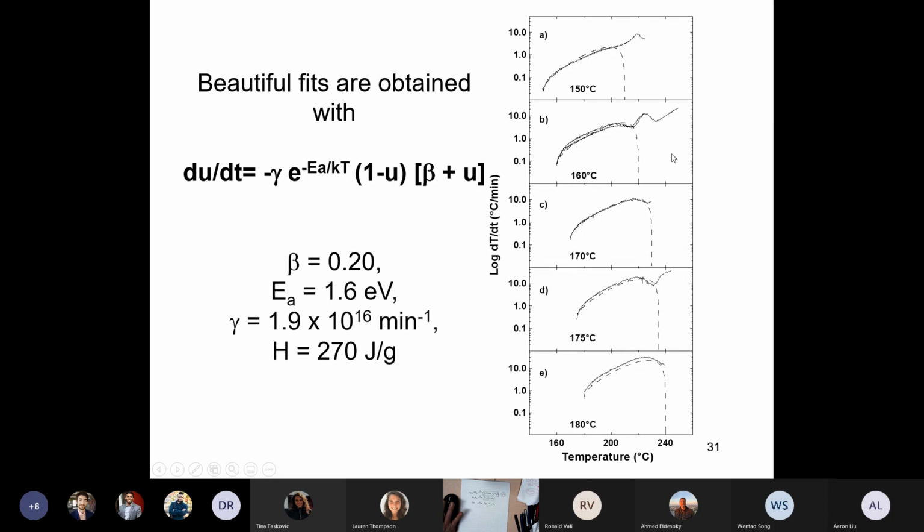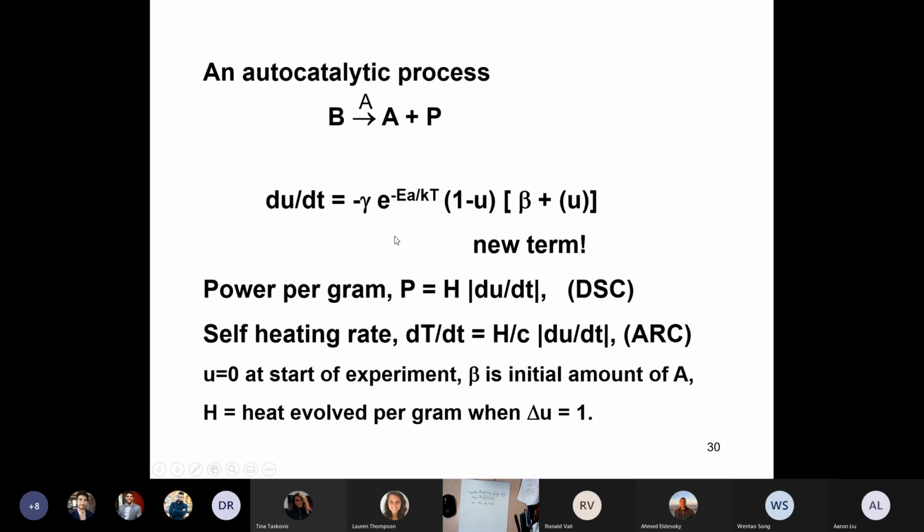And the small stainless steel container in the experiment, I think, weighs about 1.5 grams, and the sample would weigh typically 100 milligrams or less. So the majority of the self-heating, the heat is used primarily to heat that stainless steel tubing up in temperature. So you have to take account for that in your analysis. The heat capacity that you have here, the specific heat, includes the specific heat of the stainless steel tube.